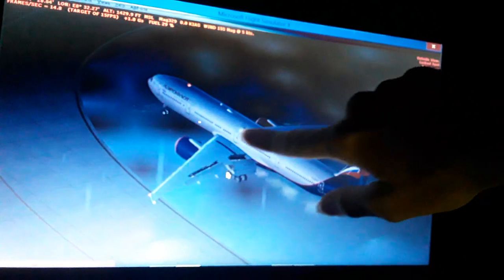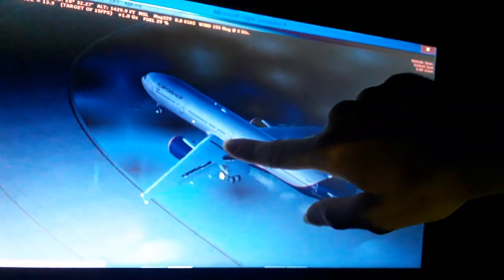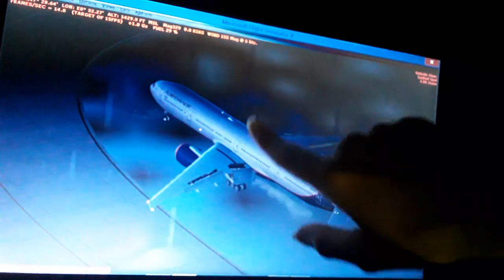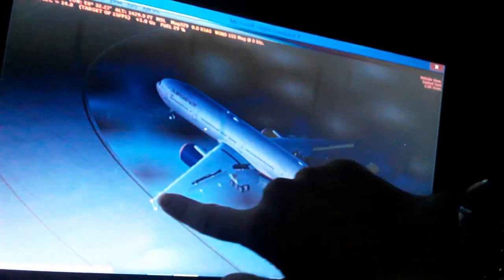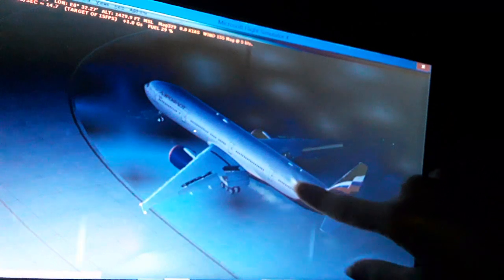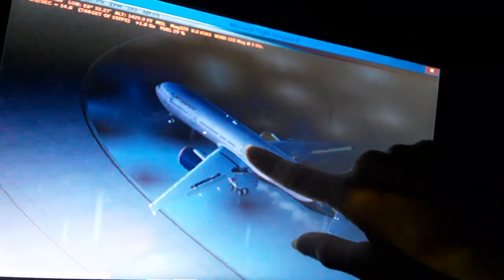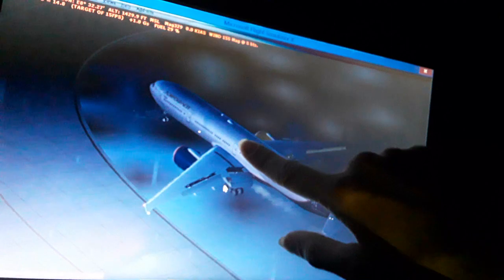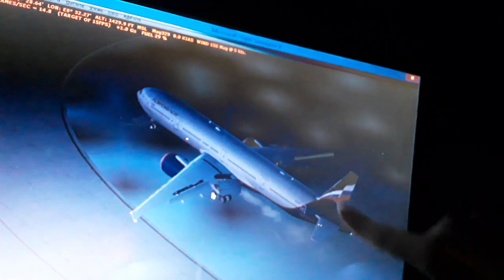So you can see here we have the outside view of the aircraft. You can see the mean aerodynamic chord position, where the maximum aerodynamic lift is created, and the vectors from the left and the right engine. The aerodynamic chord position is also where the stall begins, where the airflow becomes detached from the top of the wings. The center of gravity: transverse is this vector, from wing to wing tip, and longitudinal is the nose to tail vector. Also the lever arm from the center of gravity all the way back to the horizontal tail over the airflow,